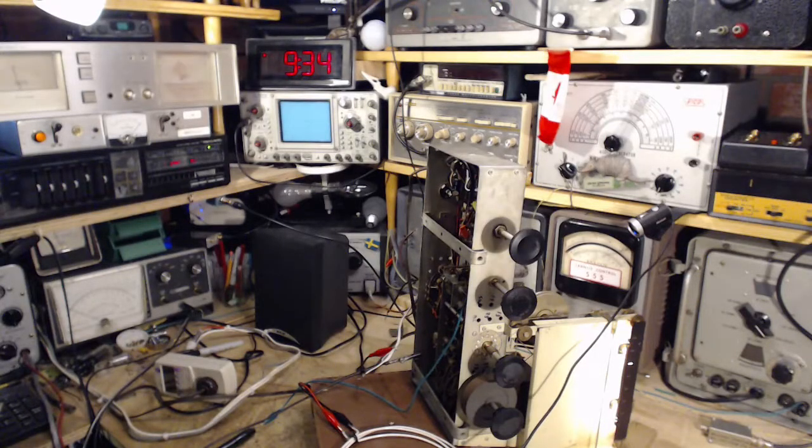Okay, after thinking about this a little bit, I think I really have to sort out what is going on with the capacitor, the tuning capacitor, and all of its trimmers completely, and get a complete grip on that. Number 2, I'm pretty sure when you align the first shortwave band, the alignment actions affect all the rest of the bands coming next. So if you don't get the shortwave band straight, you won't get any other ones straight either. So it's very, very important to get this correct. So I'm going to concentrate on trying to sort out what it is about this